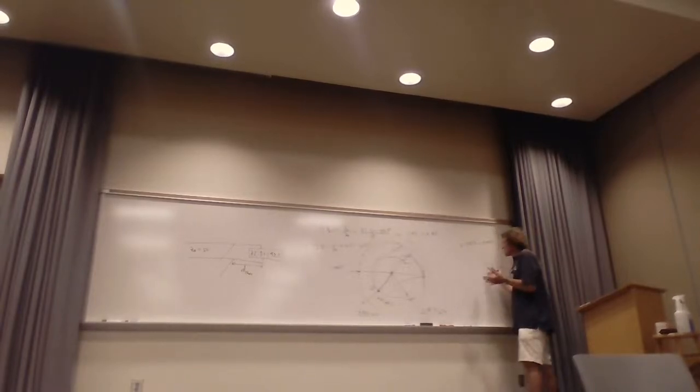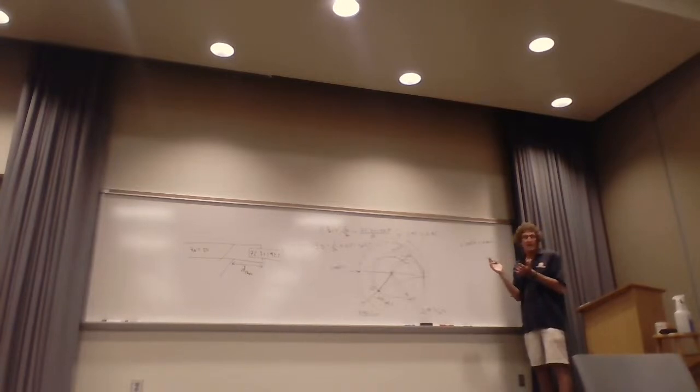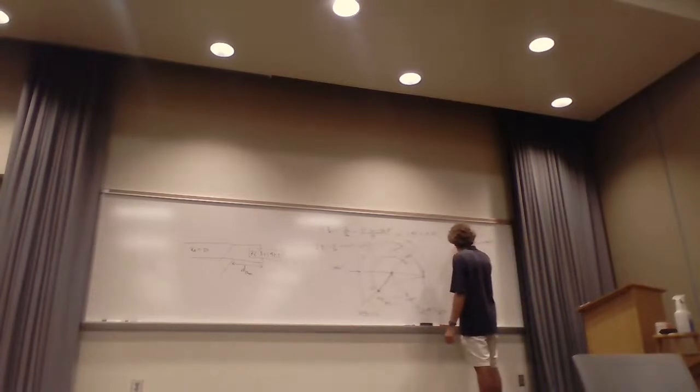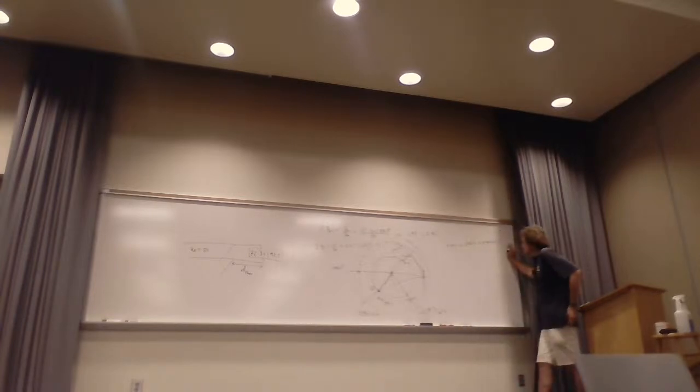0.44 lambda, but there's something that bothers you. That's a negative number, right? So what do we always do? If we ended up with a negative number when we take the place we ended up at minus the place we started, we add half a wavelength. Remember that now? Have to add half a wavelength. So now we add 0.5 lambda. Now what's that going to be? 0.3 plus 0.405. And that should be the actual distance to the attachment point, the D3.